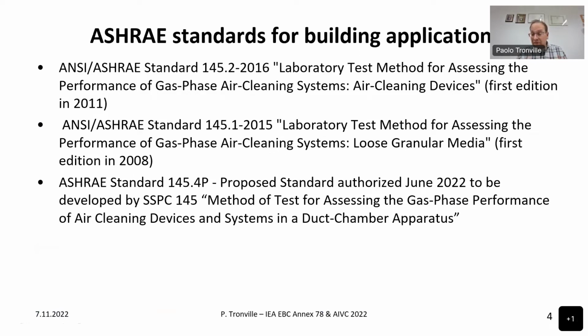This is a limited scope, because part 1 of the EN standard also covers different types of filter materials, while this one is focused on loose granular media only. However, part 2 covers the performance assessment of full-scale filter elements. It was first published in 2011 and then confirmed in 2016 with small changes.